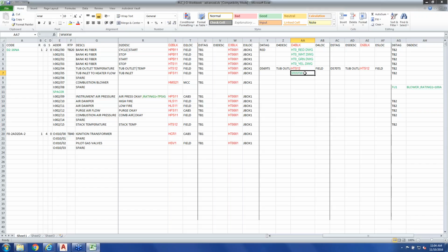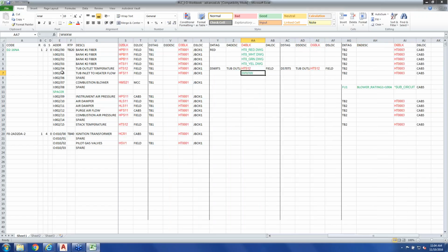So right here I'm going to have a jumper between my 5th and 6th inline device, or 5th and 6th addresses here, and I am going to use the vertical character, which is found right above your enter key. If you hold shift down, you'll get a vertical character here. And what that tells it to do is to put a wire in at that location.